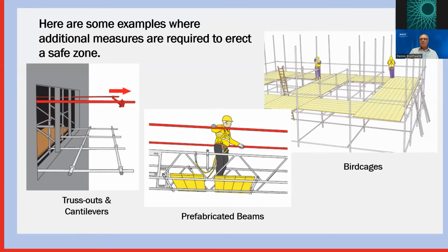Bird cages, particularly difficult because we've got a lot of area there, but we build it with wells in the middle, such that the scaffolders can gain access to every standard position for erecting the next lift.